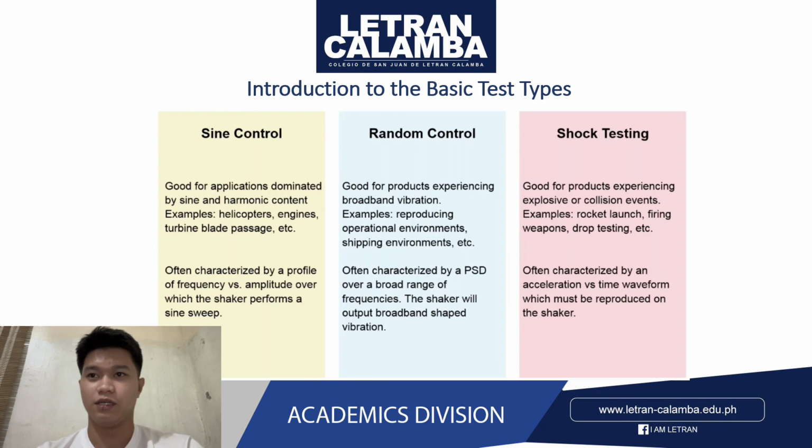Random control is good for products experiencing broadband vibration. Examples are reproducing operational environments, shipping environments, etc. Often characterized by a PSD over a broad range of frequencies. The shaker will output the broadband-shaped vibration.